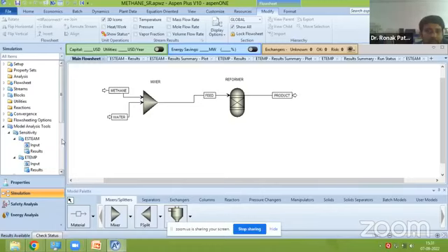And it additionally requires the sigma profile. That sigma profile and molecular structure can be generated from another molecular simulation tool, which is Gaussian. If you have heard about the software Gaussian, it gives us the sigma profile and molecular structures. And from the literature, we can identify how the density, viscosity, all such properties are going to vary with respect to temperature and pressure, right? What is the critical temperature? What is the critical pressure? All such things we need to find out from the literature and add as a pseudo component. Then we can use that pseudo component, or hypothetical component, whatever you say.